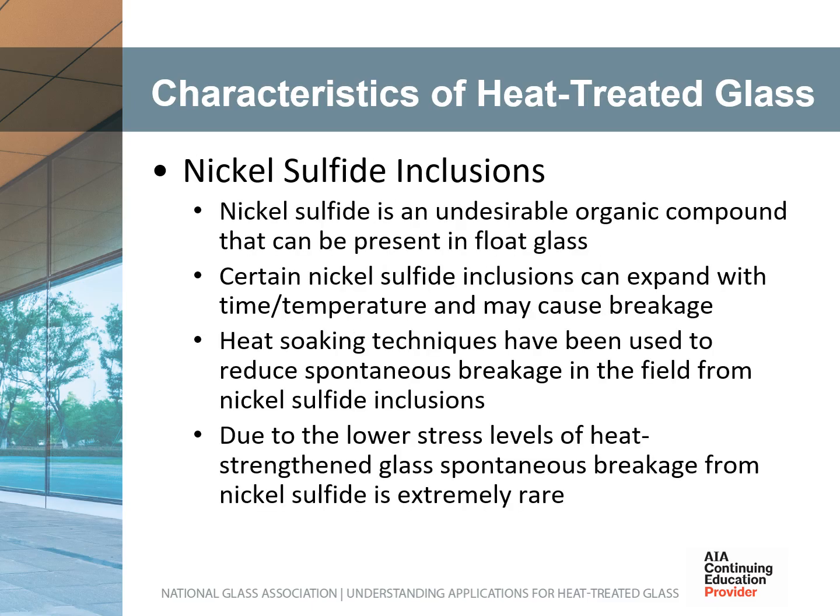As mentioned, there are various types of inclusions present in heat-treated glass, and most do not pose a risk of breakage or have any effect on performance. One exception is nickel sulfide inclusions. Nickel sulfide inclusions may be formed whenever nickel-rich contaminants, such as stainless steel and nichrome wire, are unintentionally introduced into the glass melting furnace along with the desired materials. The nickel may combine with sulfur in the furnace fuel, or the batch materials to form nickel sulfide inclusions.